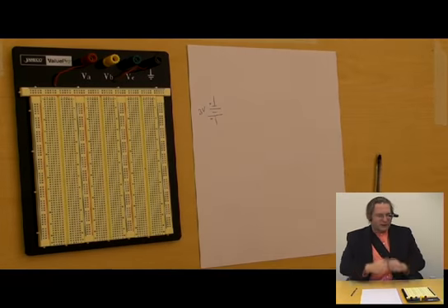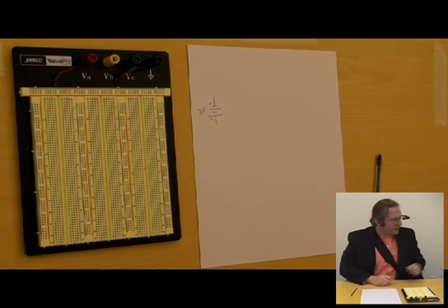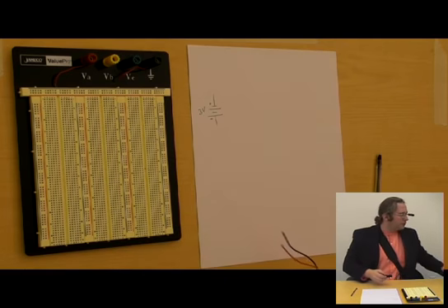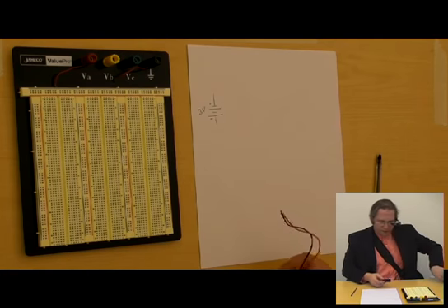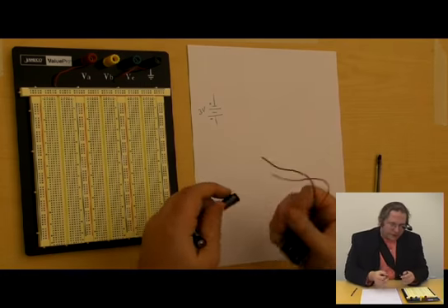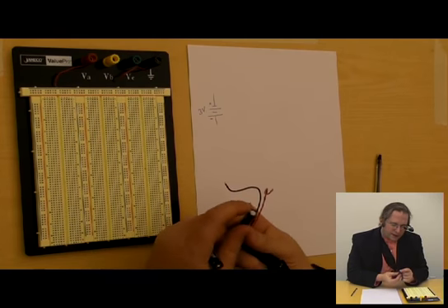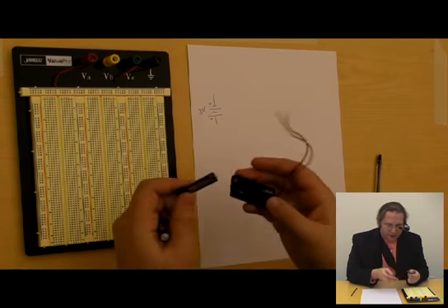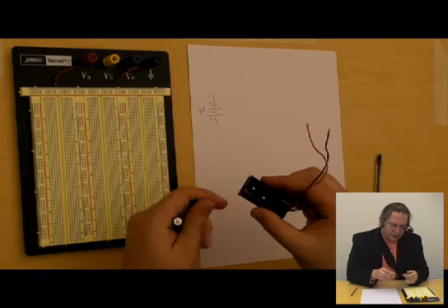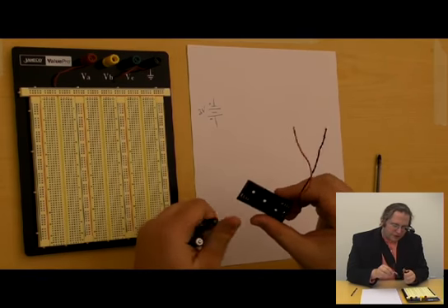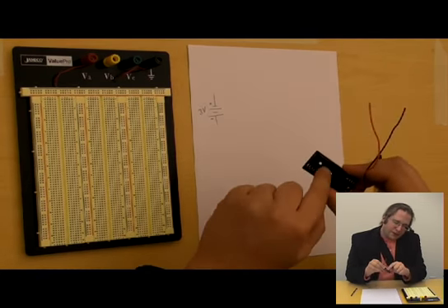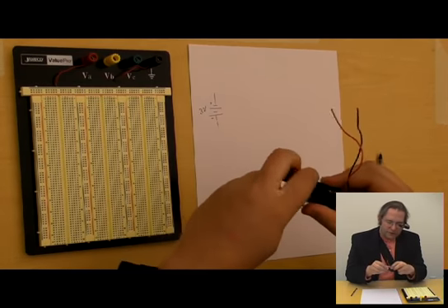Let me actually make some of these components as I'm drawing this diagram. This is a battery holder for 2 AA batteries. With these batteries, the little tip side is the positive side, and the flat side is the negative side. Generally with these holders, the spring goes against the flat side. You can even see in the holders, they have a little plus side and a little diagram of how the battery should go in.